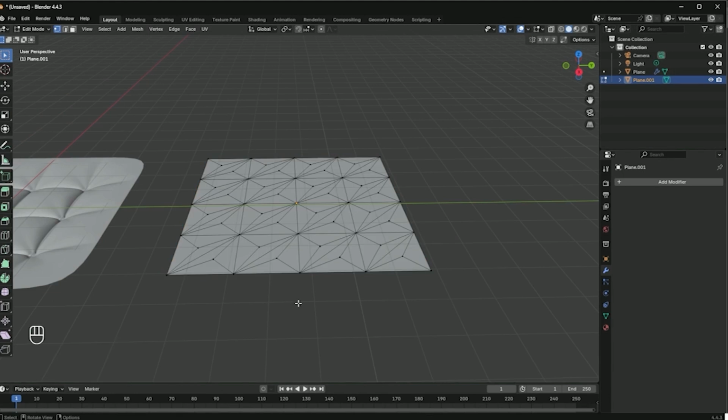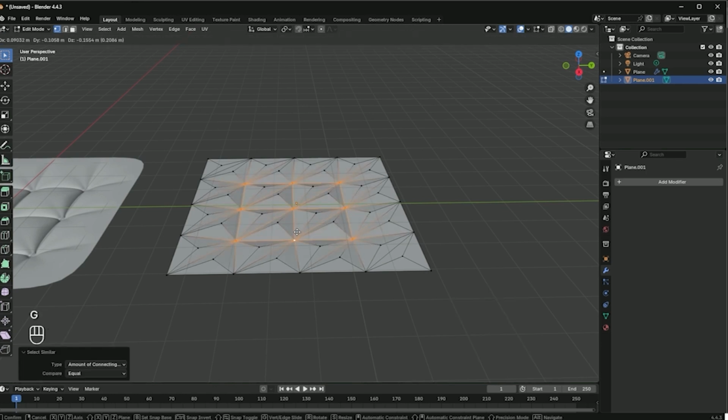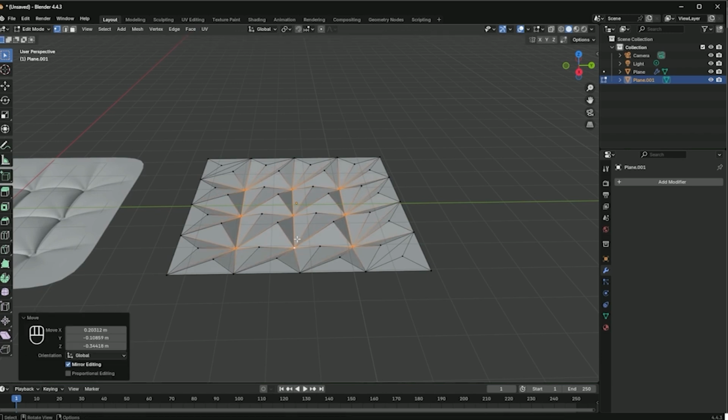First, I will go ahead and deselect the current selection. Then I am going to manually select a single vertex point on the mesh. Now, the specific shortcut key used for the select similar function is Shift+G. So I am going to press Shift+G on my keyboard right now. First, I select this option, then I move it down by pressing G. Next, I use the shortcut Ctrl+Shift+B to apply a bevel, and finally I press E to extrude the shape out.